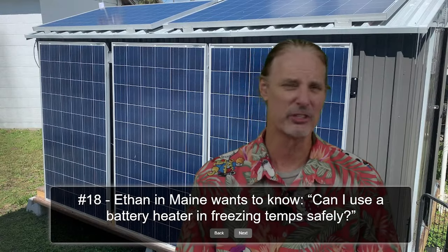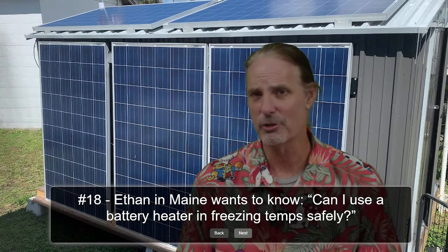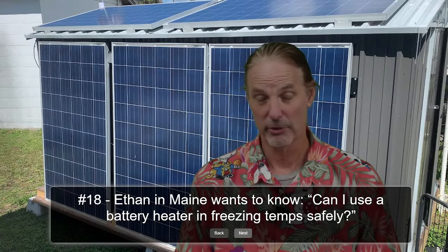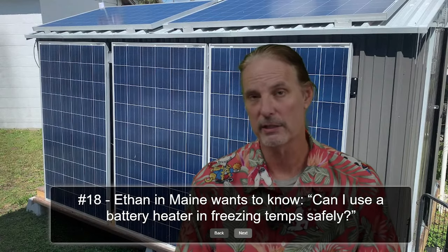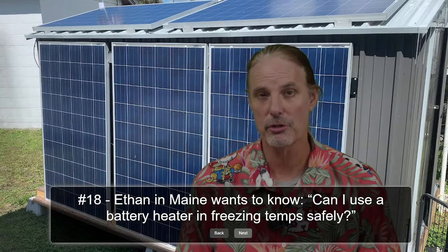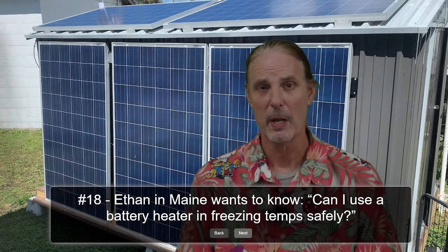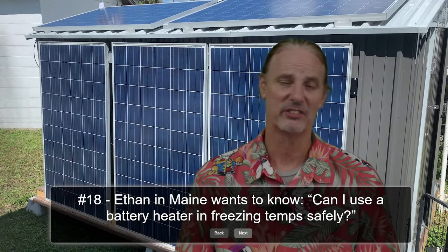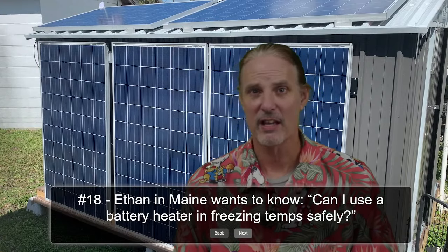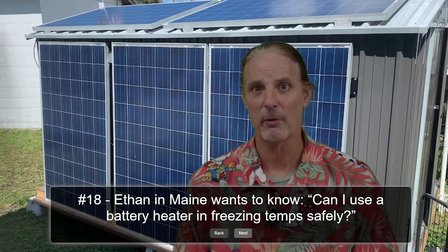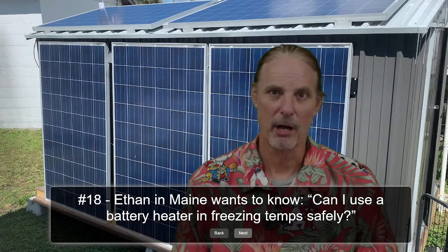Lithium batteries do not like anything below freezing. Anything below 0 degrees Celsius, or 32 degrees Fahrenheit, they don't like it. They should be cut off and should not be allowed to charge. They will discharge up to a certain extent. But most batteries these days, even the ones that are stored in your RV or something along that line, as long as you put them in an environment at or close to the environment where you're at, you're not going to run into problems with them being cold.